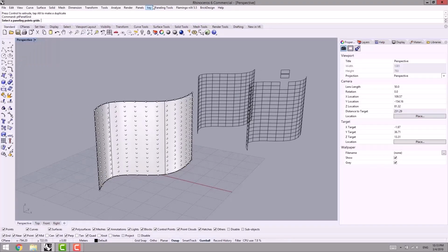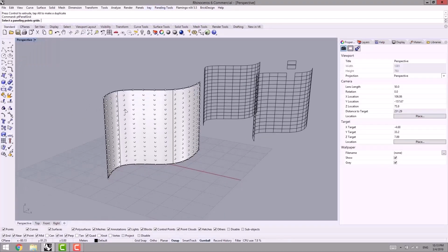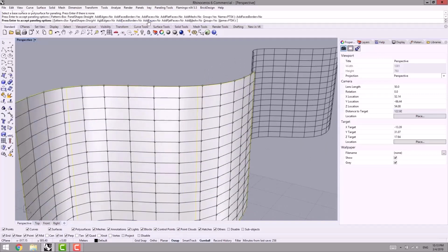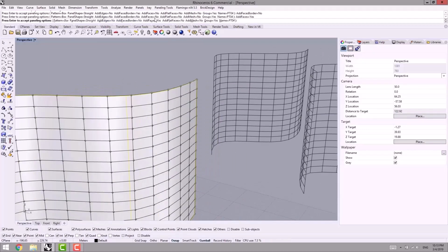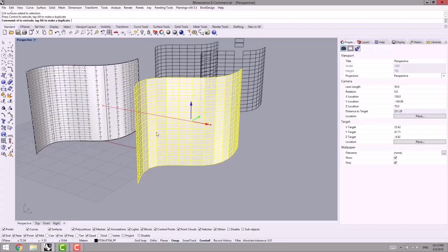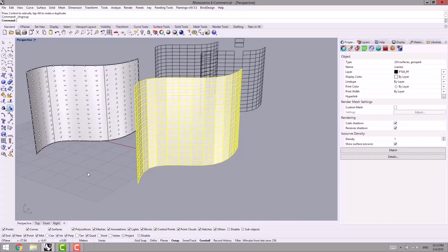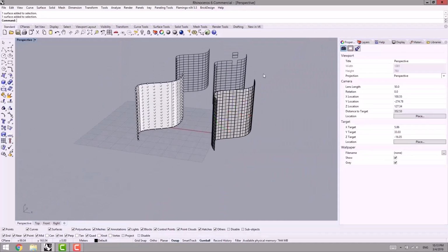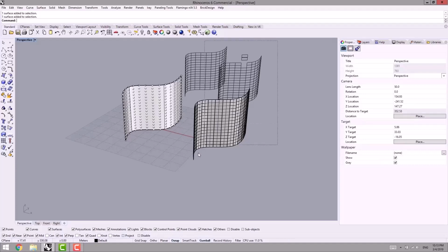Again, PT panel grid and select my points. The add face can create the points as a surface. I turn off add edge, and I select add face, and then I ungroup them, and here, as you can see, it gives me some surfaces. Now I delete what I created here.